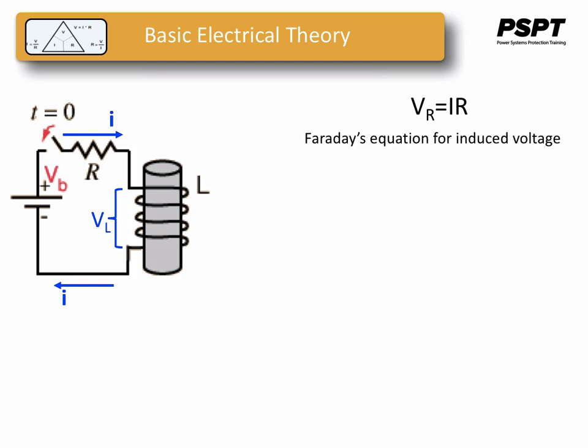Self-induced EMF in a coil is produced due to its own changing flux, and changing flux is caused by changing current in the coil. So it can be concluded that self-induced EMF is ultimately due to changing current in the coil itself. And self-inductance is the property of a coil or a solenoid which causes a self-induced EMF to be produced when the current through it changes.